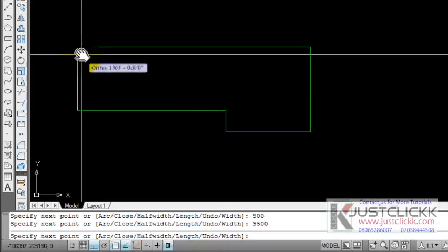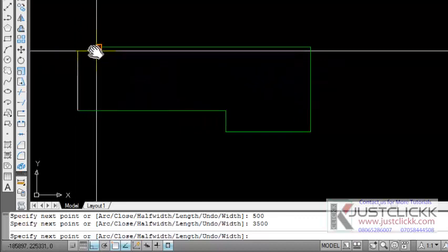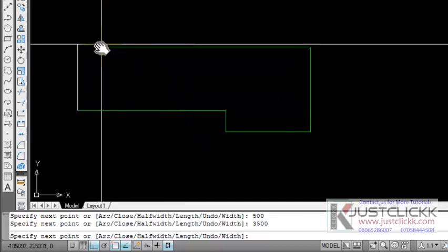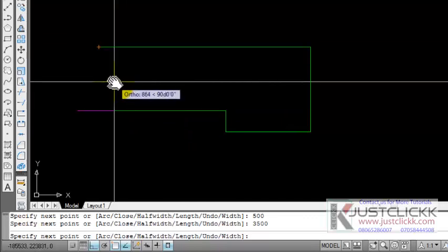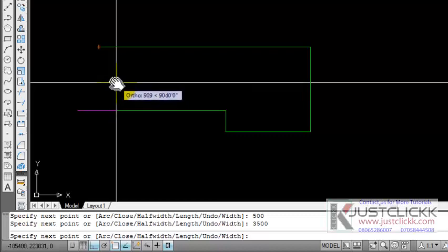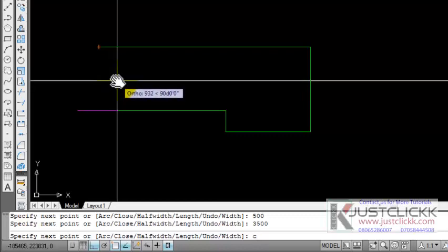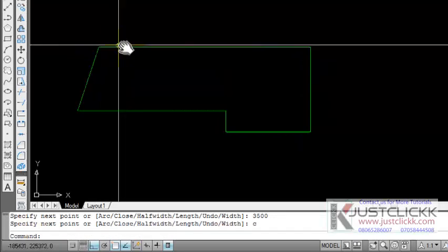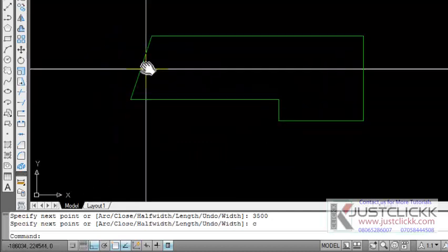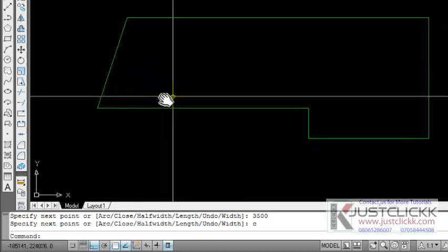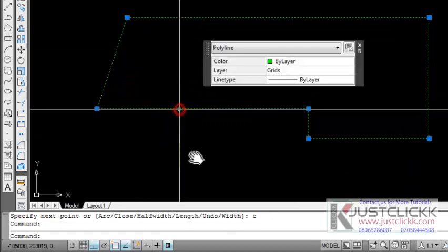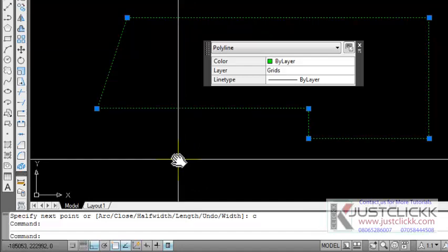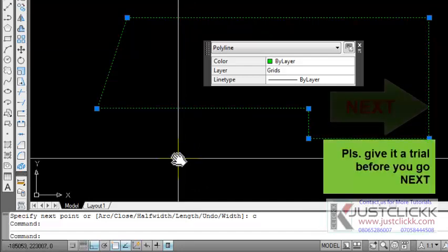And once you get to the destination here, maybe you want to close it up with this, you don't have to click. You can, if you click, it works. You click, you terminate the line, quite okay, you close it up. But then there's a special way of closing by pressing the C key on your keyboard and pressing the enter, which automatically seals it up neatly. So that's how you can make use of polyline. Like I told you, polyline, if you mouse over or you click on it, it highlights the whole object. So it creates its line with uniqueness continuously and as one object. So that's how it works.